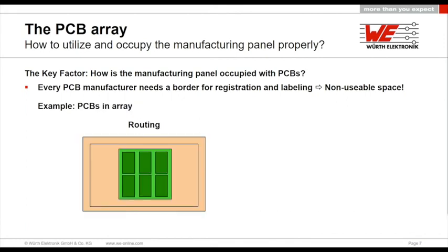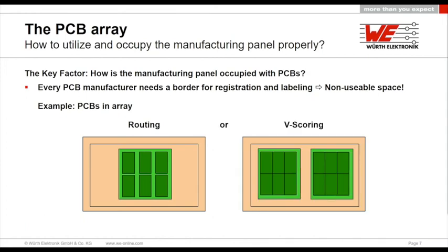We know as well that often you will not be sent out with single PCBs. Most of our PCBs are being sent out in arrays for assembly purposes, for testing purposes, and so on. And in an array, you always have an edge, and you place the PCBs in this array. And here again, a very simple example, but it shows effectively what might happen in our preparation phase.